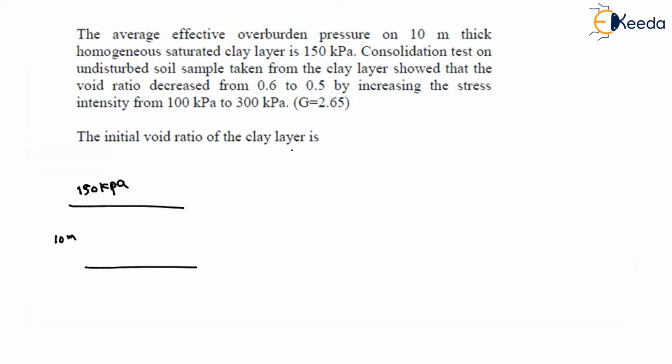Okay, fine. And what they are saying is, a consolidation test on an undisturbed sample, taken from this layer, is tested and it is observed that the void ratio decreased from 0.6 to 0.5 by increasing the stress from 100 kilopascal to 300 kilopascal.